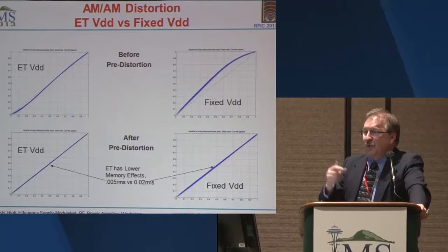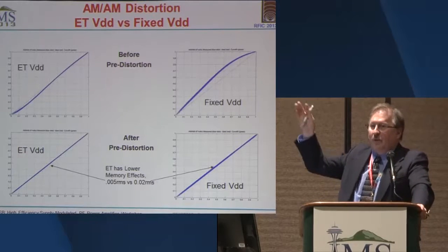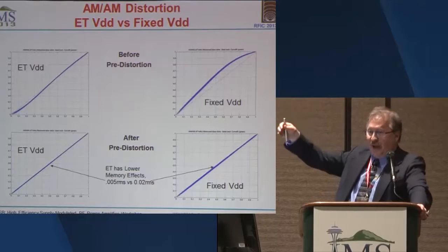So it's just that we're moving the VDD along with the VN simultaneously all the way through. And in that way, it's not showing a compression behavior, but the PA is in compression, and it is kicking up the third harmonic in that range in a much stronger way than it would normally.